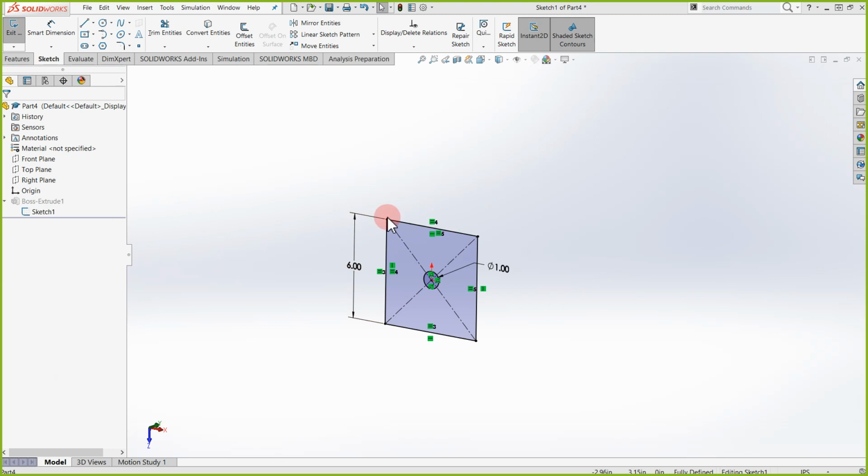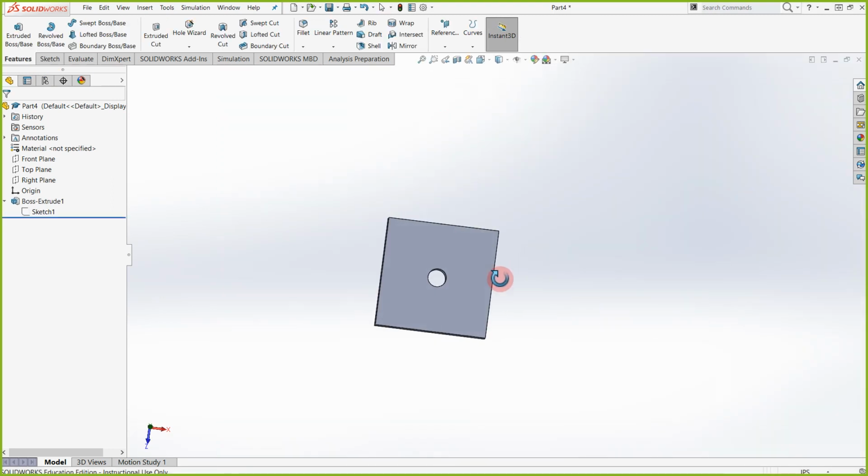When you practice this and you are modifying, and you notice that once you exit a sketch the hole doesn't move, then you may have to rebuild. You get a little stop sign light on top. That's the rebuild button, or you could press Control B, which means your computer did the piece, yes, but it didn't refresh it. So to refresh something, again, you can press Control B or hit the little stoplight, and it's going to update your 3D model.